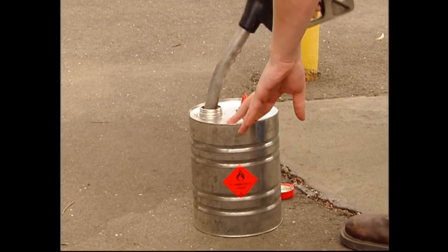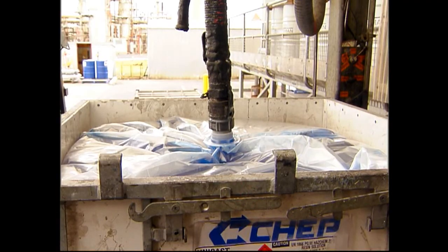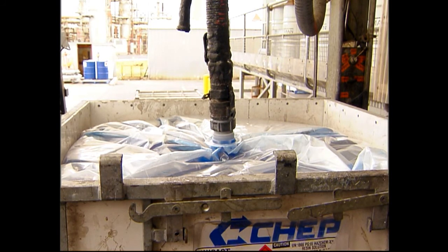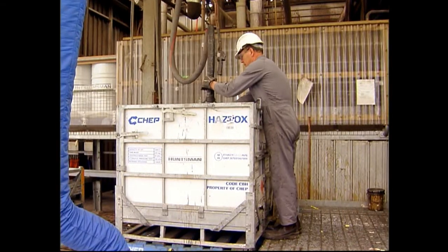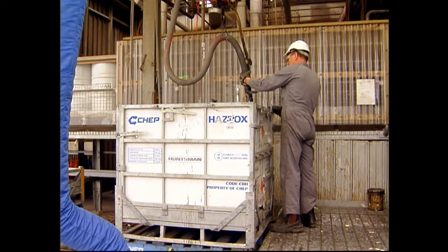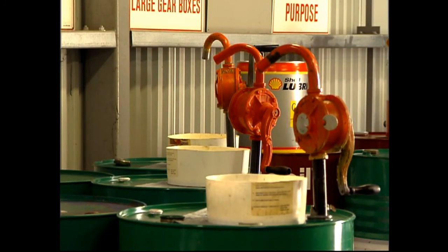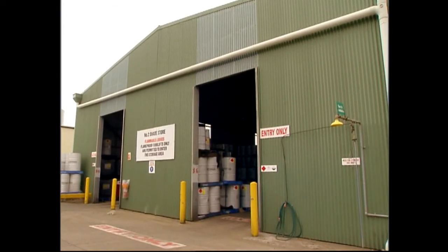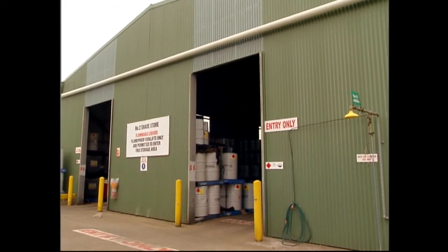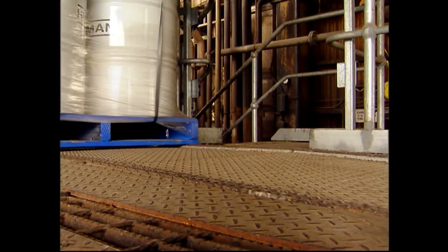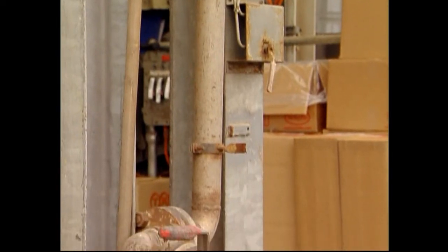Liquids, gases, dusts or powders that are being transferred, discharged, decanted or processed all have the potential to generate static charges. Again, consideration should be given to the speed or velocity of these activities. Nozzles that are used should be made of conductive materials and in some cases may need to be bonded or grounded. Generally, objects nearby or directly involved with processes that include the movement of liquids, gases, dusts or powders should be made from conductive materials and be grounded.